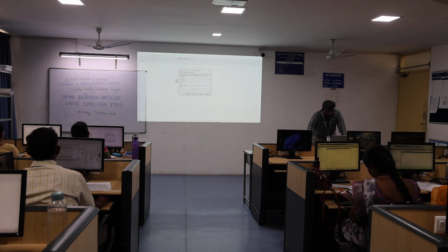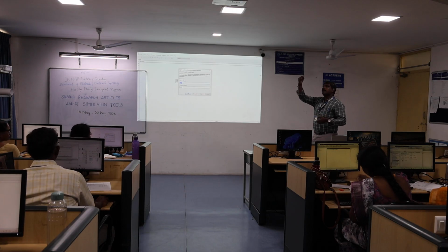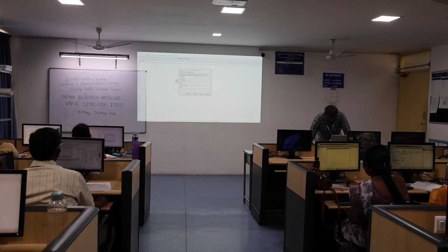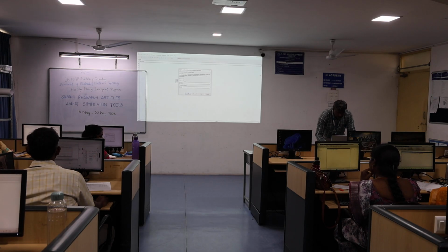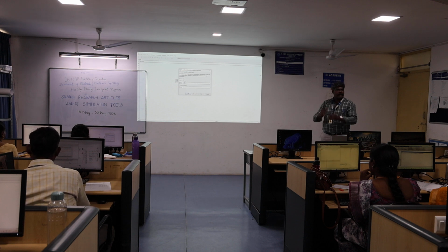Okay, let us start with time value 0, output value is also 0, right? Next, first we are going to start the triangular from 0 to 0.3, then again 0.3 to 1, right? Now move on to here. Starting time is 0, again output value is 0. Then time value 1 e power minus 3, divided by 2. You have to take it as 50% of the total time period for the next level.